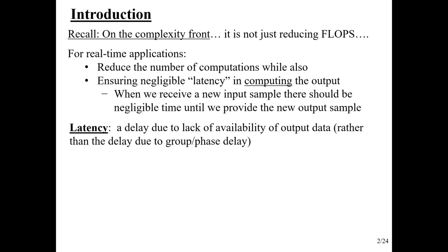So latency is just a general term that means a delay due to the lack of timely availability of output data. And this is different from the delay that we talked about that's inherent in a filter, that's group and phase delay. That's not what we're talking about here.